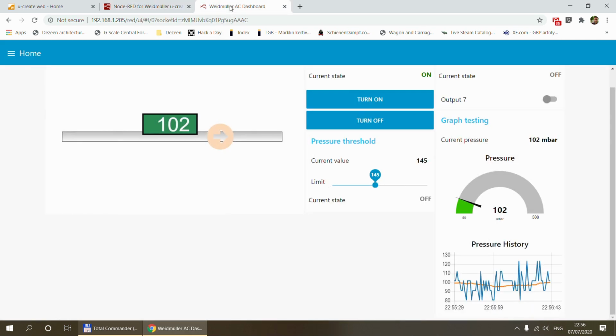So let's see how it all works in real life. I'm just going to remove the cap from the pressure sensor, and I'm going to apply some pressure. By the way, now you can see how nicely the live value and the last 50 average show that it's a much more constant value. So now I'm going to apply some pressure. And now you can see the live data going up. And then slowly but surely the average is going to follow as well.